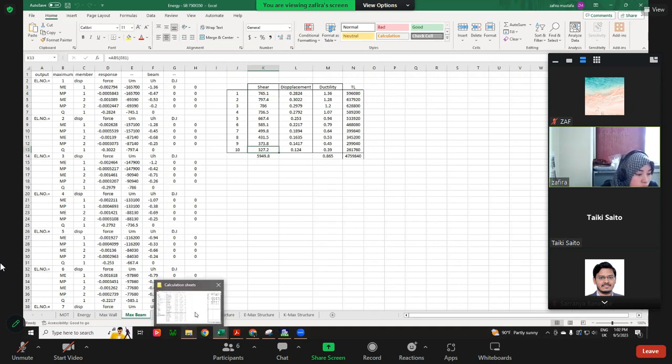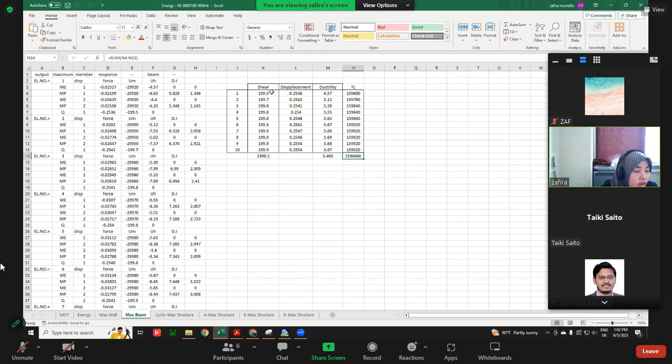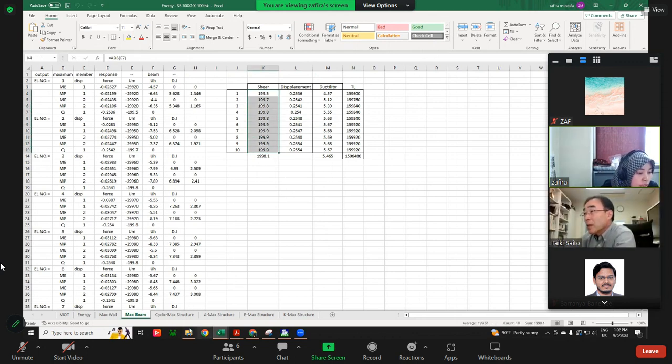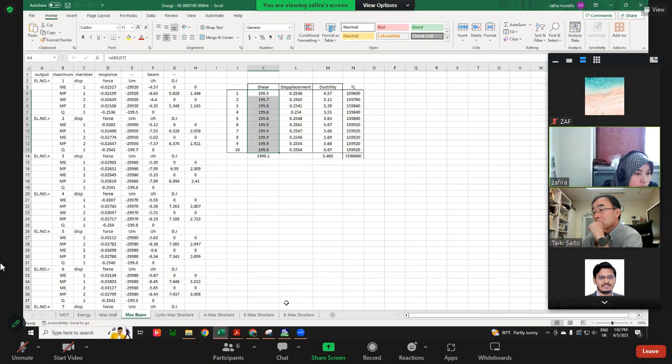And then I try to compare with a smaller beam. This one is a 300 by 100 steel beam. We can see almost every beam reached its maximum, around 200 kilonewton. But if we design the beam with 750, not every beam reaches the maximum capacity, and the ductility is also small. If we compare to the smaller beam, the ductility is quite big, like 5.